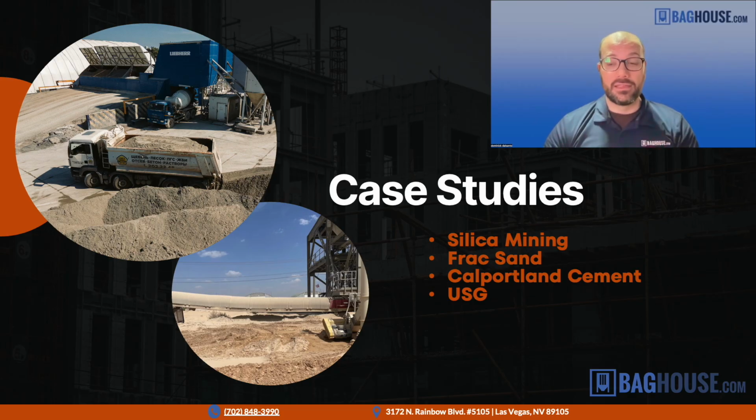Moving to cement, one of our customers we worked with for many years, Cal Portland Cement, at several of their facilities. Something particular we did with them, for many years we did service work for them. So we conducted the filter changeouts on many of their large reverse air baghouses. For example, their large plant in Mojave, California, a couple thousand reverse air bags needed to be changed with big J rods and springs and things like that. So quite a big production.